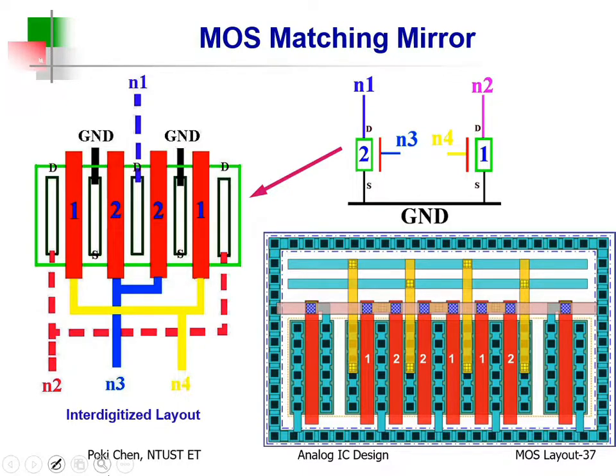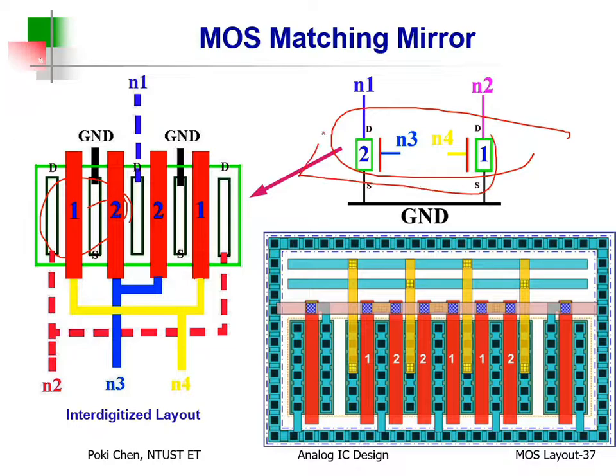But this is some kind of wrong example, right? It's so simple, 1 and 2. The differential pair, for example, and how to make the common centroid. I told you already, 50%, 1, 1, then 2, 2, right? You make this. But I leave this page for you on purpose because something is wrong with the layout.